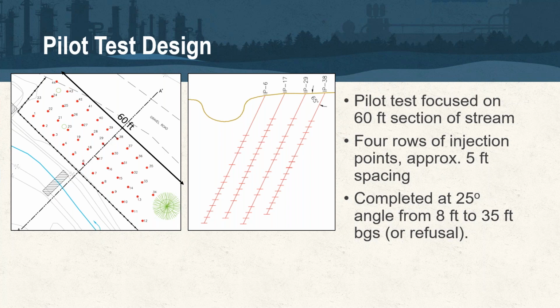In that situation, we would default to a much tighter spacing, probably something on that 5 foot end, the 5 foot range. Then as you go deeper, and so if you're working at 20 feet below grade or deeper, that spacing is gonna increase, 7.5, 10 feet.